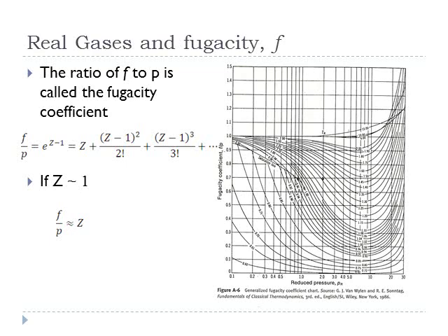It's really when you start going away from z, and that can happen for a number of different reasons. So what we have here is reduced pressure, which is equal to the pressure divided by the critical pressure. And the other variable on this graph is the reduced temperature, which is the temperature divided by the critical temperature. So you can see for a lot of substances where you're near the critical temperature and pressure, you can start getting major deviations where z is no longer near 1.